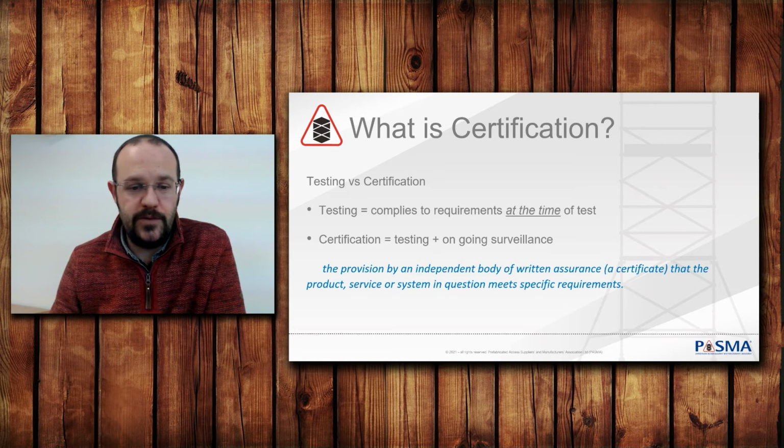Under Belgian law, all products placed on the market for temporary work at heights must be safe, Codex Book 4. Many manufacturers, including those of mobile towers, also have their products independently tested. Through independent testing, they can show to their customers the product conforms to standards like NBN EN 1004. This gives confidence to the supply chain and ultimately to the end user that they are using a good quality product.